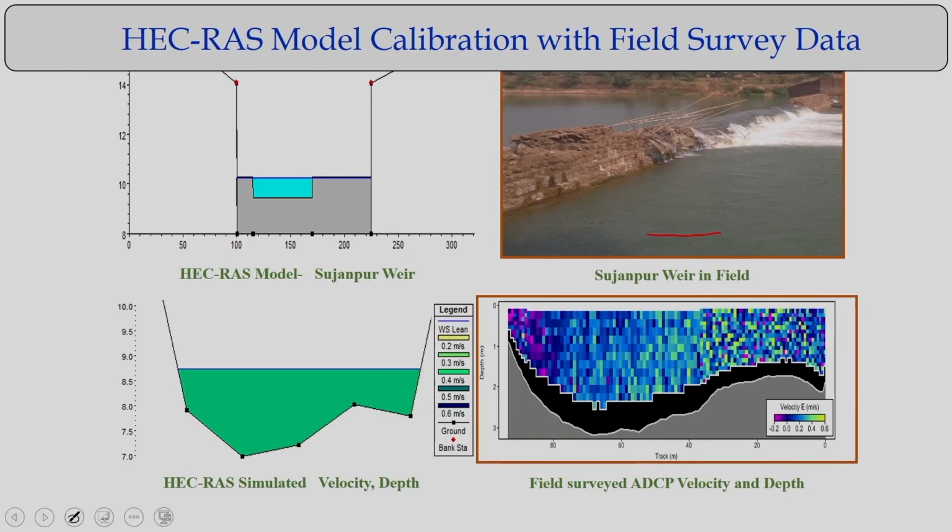This is the real condition where you have the breaching of the weir, the old weir breaching part. The same things are there in the HEC-RAS model setup, how we have put it, how this velocity was measured, and how the velocity is simulated. So one is the field condition, and another is the HEC-RAS modeling setup. Those variations you try to reflect, how it looks in field conditions. When you observe, this is the field level photographs and velocity measurement, and this is the one dimensional HEC-RAS model output. It shows how things differ when you do the modeling of the Saint-Venant equations.